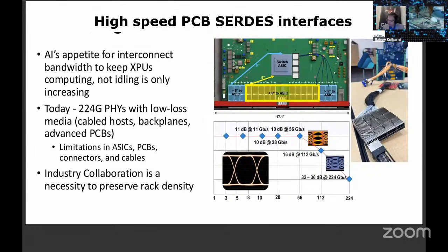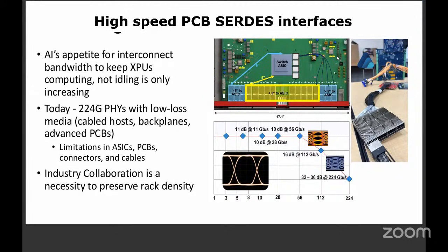Can we go to the next slide, please. Yes, already did. Here I'm showing how it looks when we implement this kind of module in a server class PCB. It is just a schematic, a theme actually, not the actual PCB. We have shown an ASIC at the center, and then we are fanning out, and all these fan outs have to be length matched. This type of PCB is used mostly in AI, especially AI backend. These are used at 224 Gbps right now.